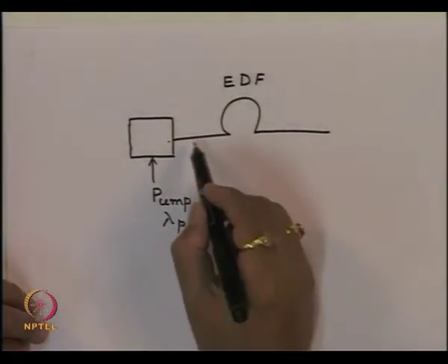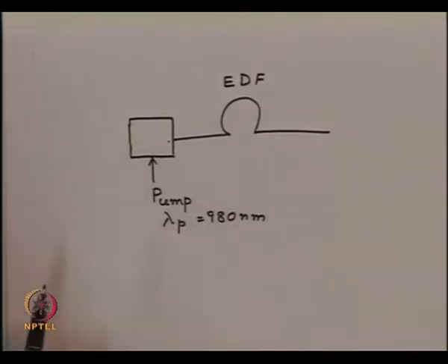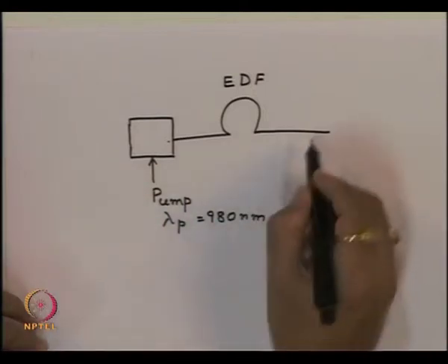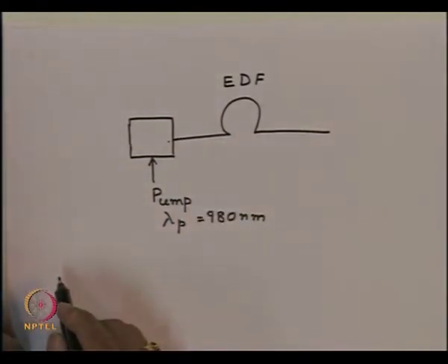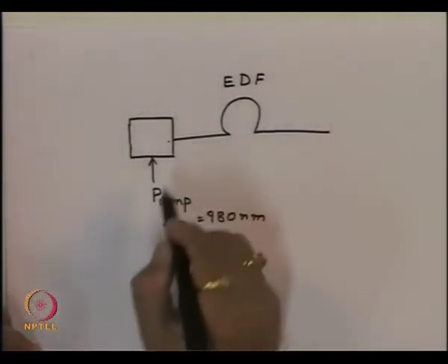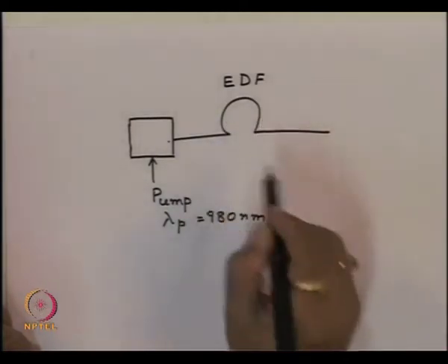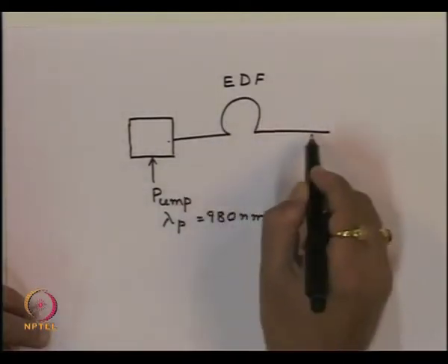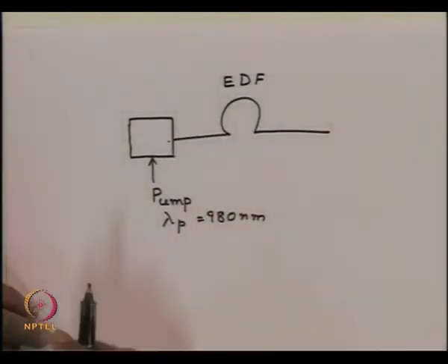Now since we are having a medium here which is amplifying, and the gain of this amplifier is very large, even a small reflection because of any deformations in the fiber or something may have a feedback, and since the gain is very large, there is a good possibility that this signal which is fed back because of small reflections, it may put this whole device into oscillation.